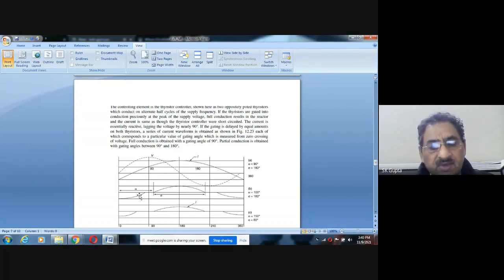पूरा कंडक्ट. If the firing angle increases beyond 90 degrees, तो conduction आपका थोड़ा कम हो रहा है, देखिए. So this is the relation between firing and conduction angle. ये firing angle, अगर 90 degree होगा तो ये पूरा हमारा 90 का बनेगा, ये बनेगा full. Conduction angle means conduction current will flow continuously from end to end. If the firing angle is increased, तो conduction कम होता जाएगा.